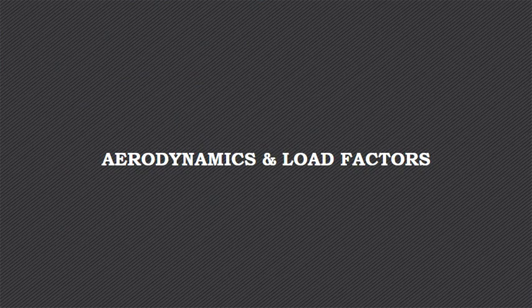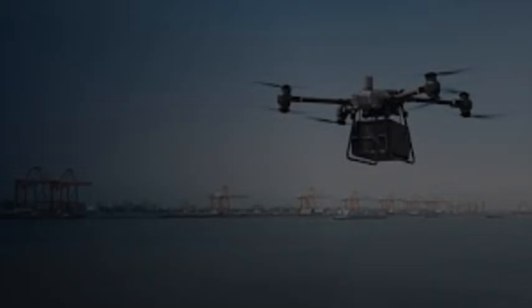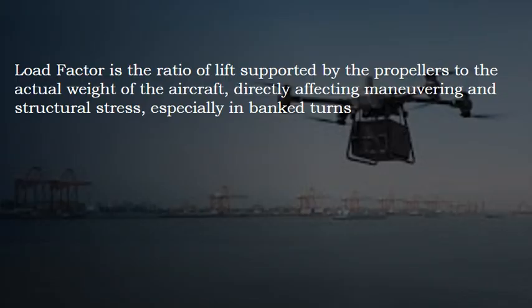Next, let's look at aerodynamics and load factor. Aerodynamics is the branch of fluid dynamics studying how gases, particularly air, interact with moving solid objects, such as sUASs. Drone load factor is the ratio of lift supported by the propellers to the actual weight of the aircraft, directly affecting maneuvering and structural stress, especially in bank turns. It increases with bank angle, requiring more thrust to prevent altitude loss, which can lead to accelerated stalls.